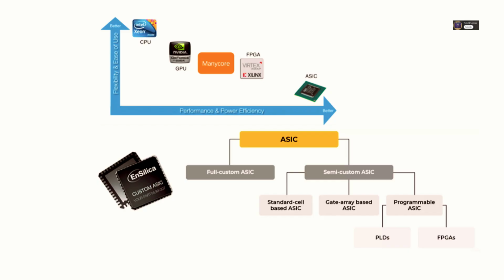application-specific integrated circuit. The ASIC is, well, it's fixed perfection in a way. It's custom-built from the silicon wafer up for one single job. One application. And once it's made, that's it. It's permanent, can't be reprogrammed. But because it's perfectly optimized, absolutely tailored for its one task, it achieves the highest performance per watt, the lowest power consumption, usually the smallest physical size, too.